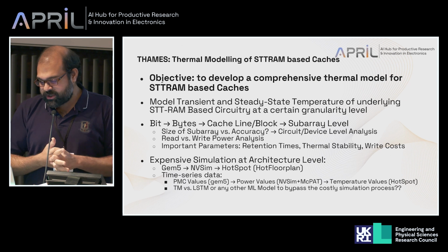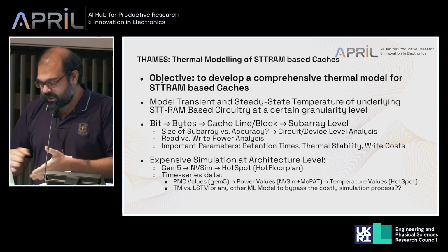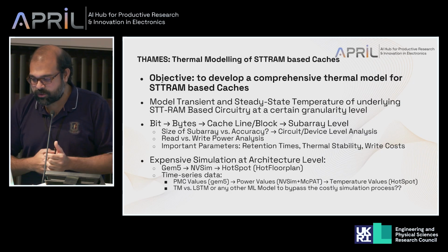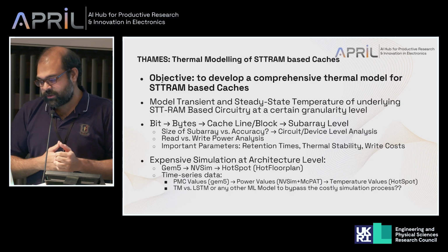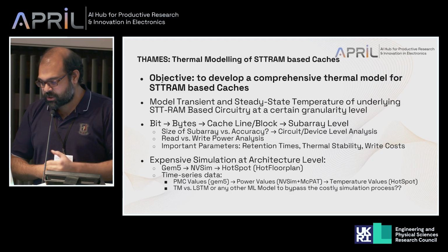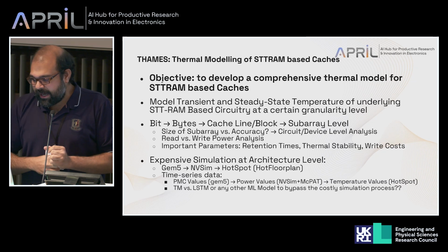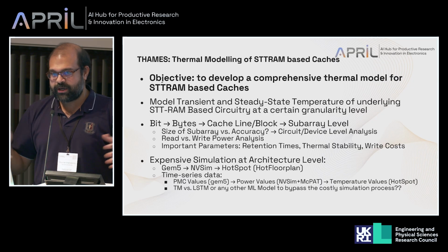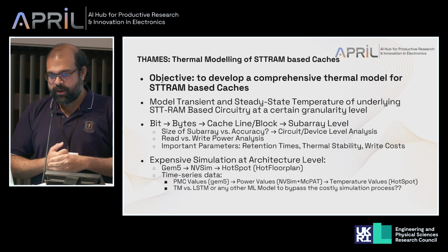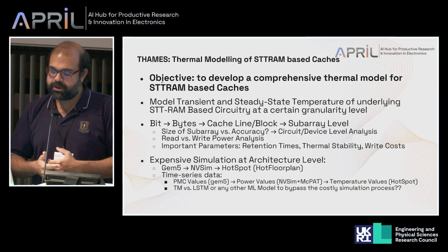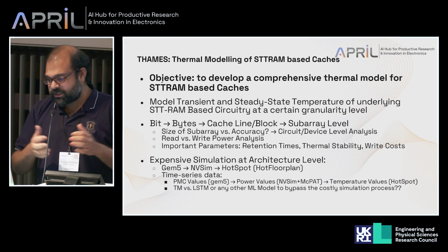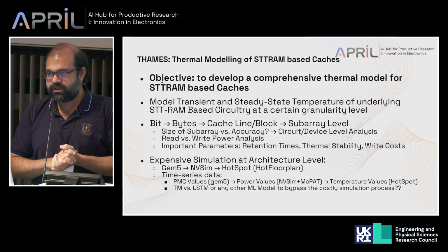And finally, we're going to generate some time series data. That is the next part of the work. So there are PMC values, followed by power values, including the McPAT simulator as well for the full system simulation in terms of power and area. Finally, once the temperature values are generated by HotSpot, we'll figure out how we can reduce the entire simulation time by incorporating machine learning models. The Tsetlin machine is one of them. Also, as it is time series data, we can use an LSTM model or any other machine learning model to bypass the costly simulation process.